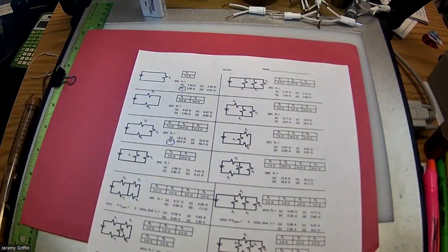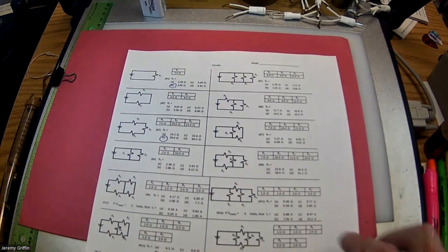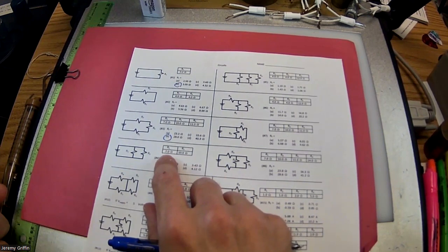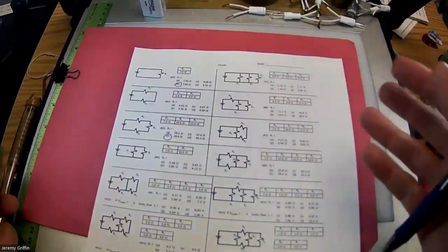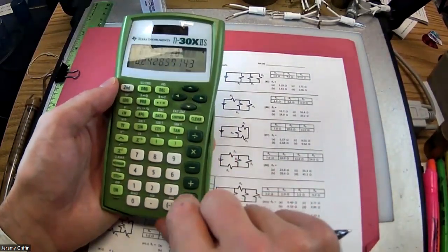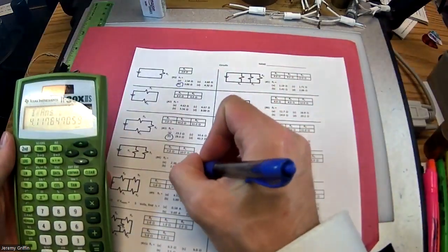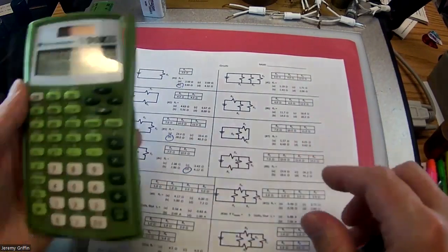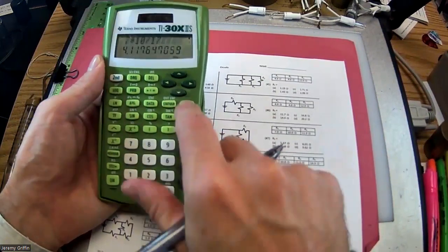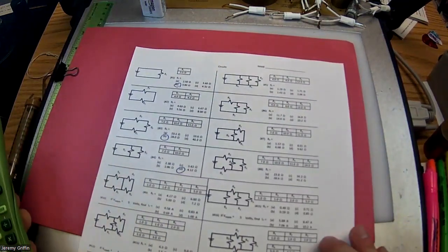Okay. Let's look at one of those. So one right beneath it, number 4. You guys see 2 resistors in parallel? Okay. Now in parallel, we're going to treat this as the same math as like 2 guys painting a fence, right? So one guy takes 7 hours to paint the fence, the other guy takes 10 hours to paint the fence. They make a 2-man team, as long as it takes them to paint the fence. Okay. So here, you can either do 1/7 plus 1/10, and then take the reciprocal of that and get 4.12 ohms. That's 4.12 ohms. Right? Or since there's only 2 of them, you could do product over sum. So you could do 7 times 10 over 7 plus 10, and it's the same thing. Okay, you guys see it's the same thing? Product over sum. You guys see that?